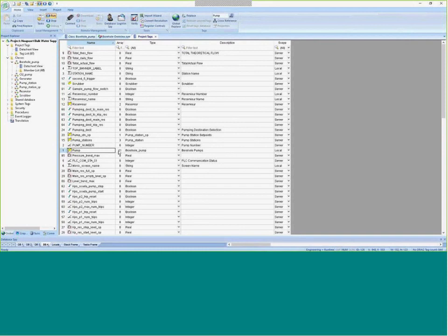Over here you can see we created an array of 11 boreholes, which is from 0 to 11, giving us the 12 boreholes. Then we have an integer, which we call the pump number. When we load the screens, all we do is pass a number to the integer, which then populates the screen with the required information from the borehole that was selected.